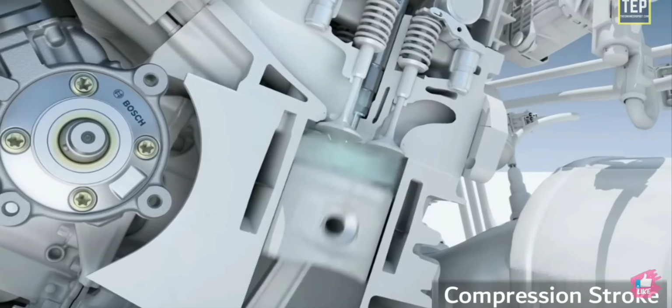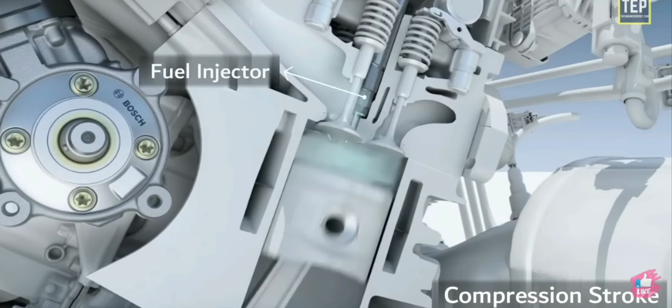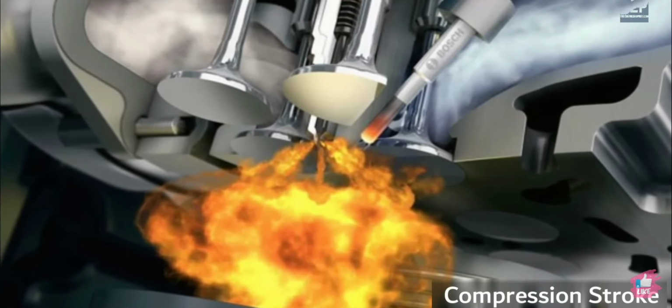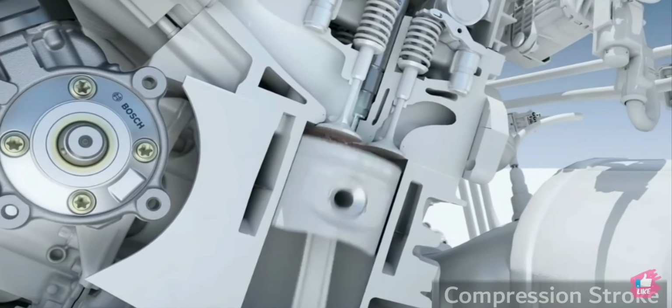Just before the piston reaches top dead center, diesel fuel is sprayed inside the cylinder. The fuel is sprayed by means of a fuel injector at a very high pressure, overcoming the pressure of the compressed air. The fuel gets mixed up with air, which contains oxygen. Since the fuel is a hydrocarbon, the temperature of the compressed air is sufficient to initiate combustion, and the fuel is burnt.